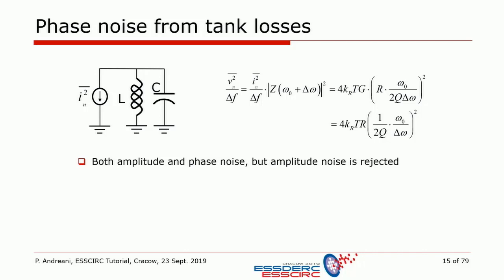we are interested only in half of this noise, because we assume that the noise does not have any preference whether impacting the phase of the oscillation or the amplitude of the oscillation. Now, if it impacts the phase, then we have to take that into account. If it impacts the amplitude, to the first order, this is actually eliminated by the oscillator itself.